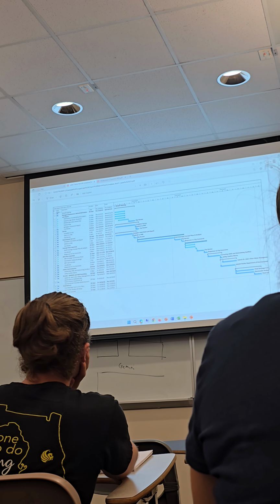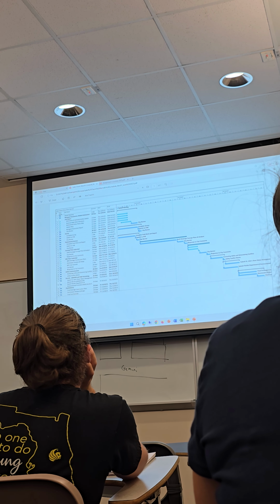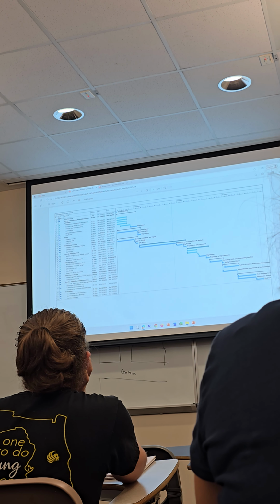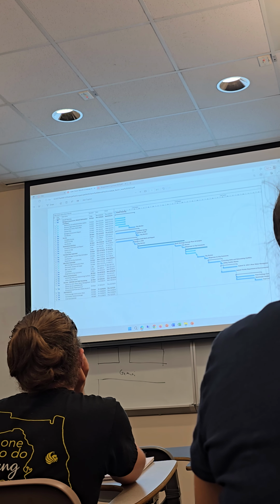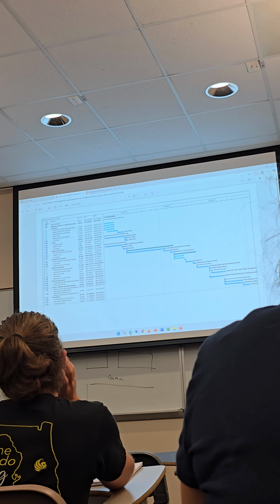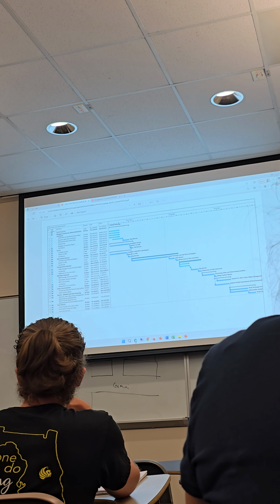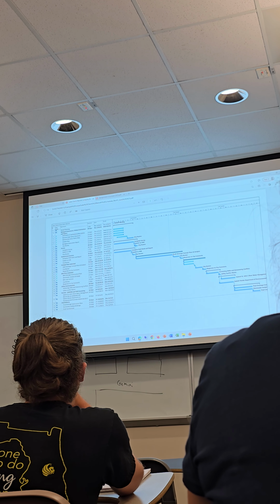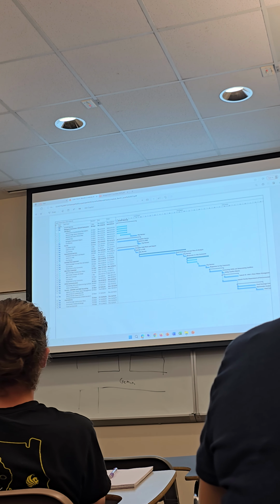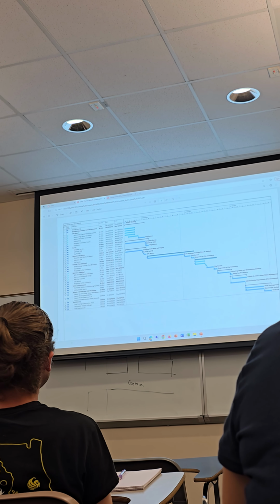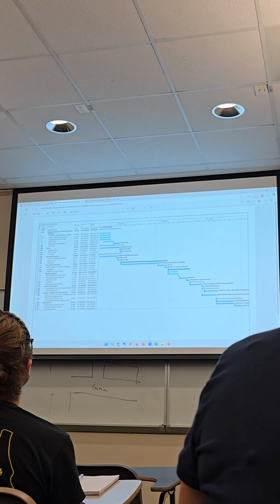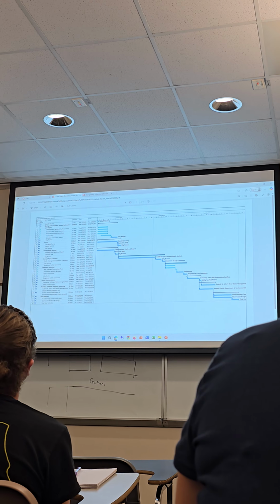And then a 60% set of plans, and then a final set of plans. And then try to estimate what you think it would take to permit your project. So that would be through city, county, and the water management district. Okay? So your schedule doesn't need to be this elaborate. You can do it in Excel, that's fine. But the whole goal here is for you to think through what it would take, thinking about your project from beginning to end. How long would it take to go through that process?